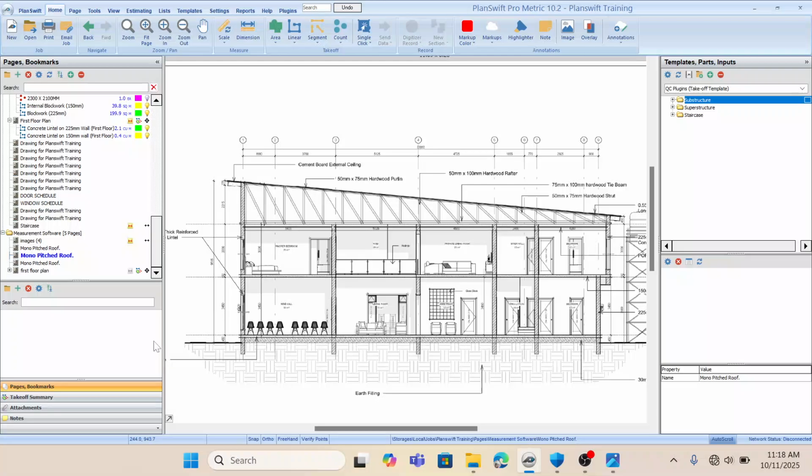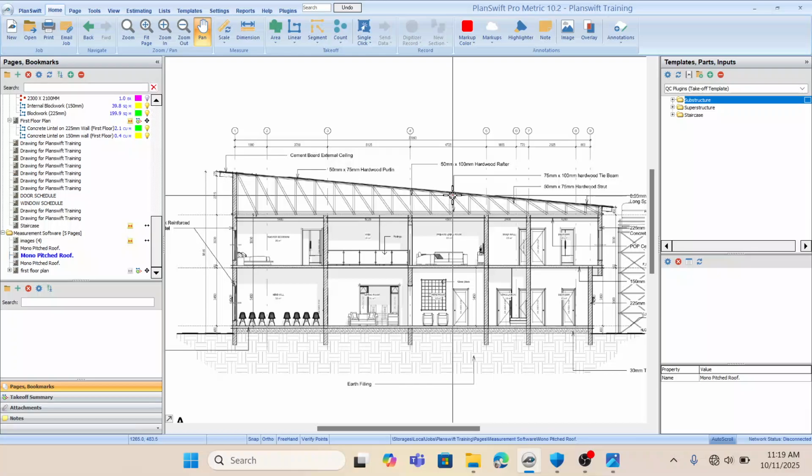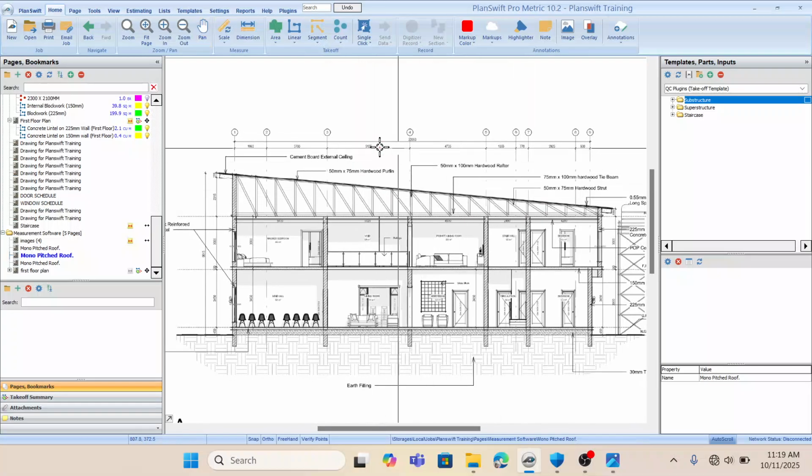If you want to make use of 1.2, we need to calculate the number of setups we have, because the rafter alongside the tie beam and the strut are an entity. Let me put it that way. You have this same setup here at intervals of 1.2, or as the case may be, more or less than that. But we're going to assume that the spacing between this setup and the next will be 1.2. They didn't state it here, but normally it should be stated.